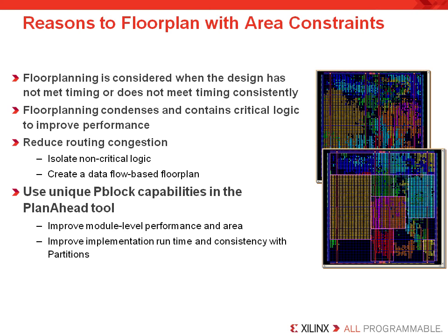Floor planning, if planned properly, can reduce routing congestion. You can use unique P-block capabilities in the Plan Ahead tool. We will discuss P-blocks in the how to make area constraints with Plan Ahead module.